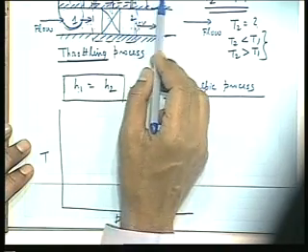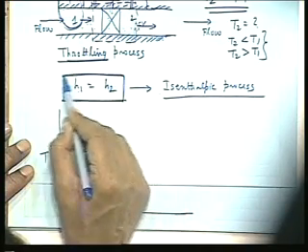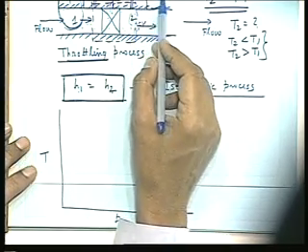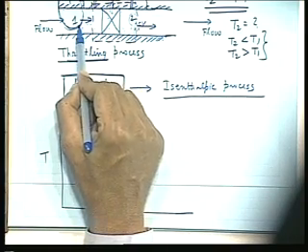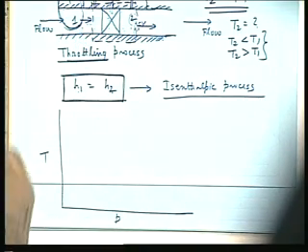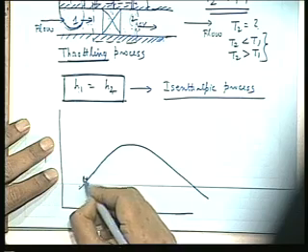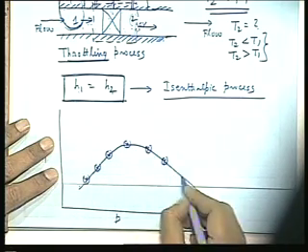so that I get different pressures and temperatures here, then since the basic energy equation for this process is H1 is H2, I can tell that all the values of enthalpy corresponding to different pressures and temperatures will correspond to the enthalpy at 1, which is kept fixed. That means I can generate different state points with varying P and T, but with the same enthalpy. By doing so, we can draw a curve which is nothing but the locus of the same enthalpy. You understand this thing?